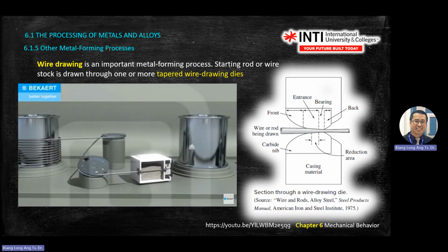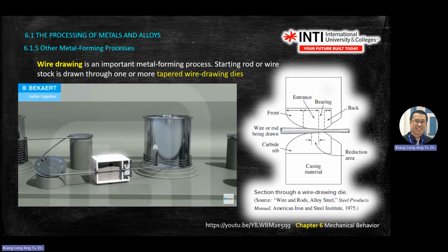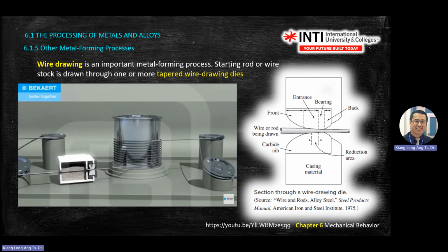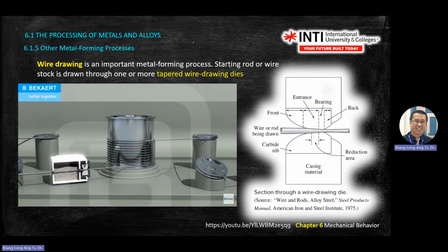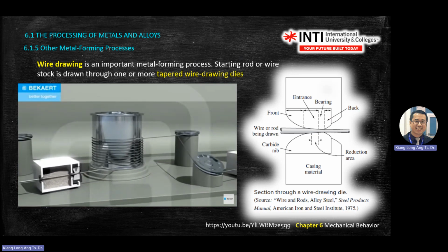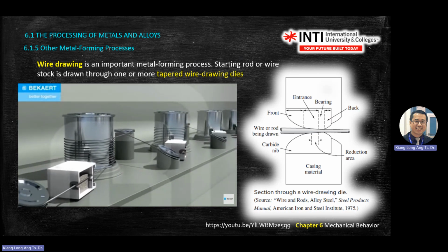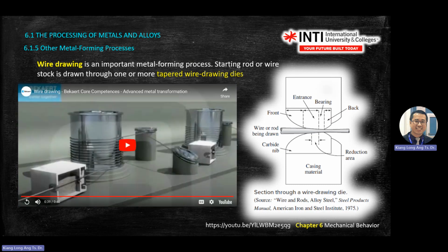One meter of 5.5 millimeter wire rod can be drawn to 30 meters at 1 millimeter diameter, then to 484 meters at 0.25 millimeters, reducing the diameter again. The process increases the tensile and yield strength while reducing ductility. The big drum here is to reduce space actually. They don't need a very long space to do it. You just wire it and wire it.